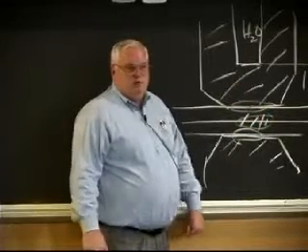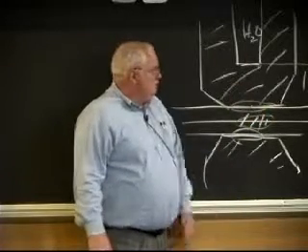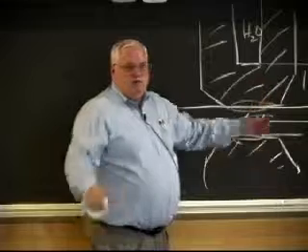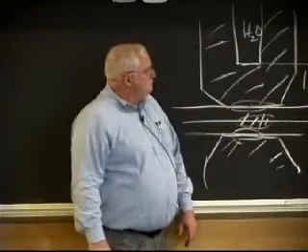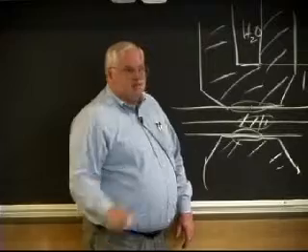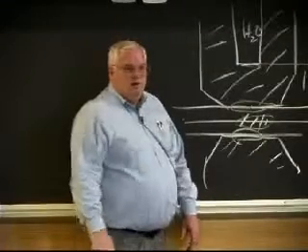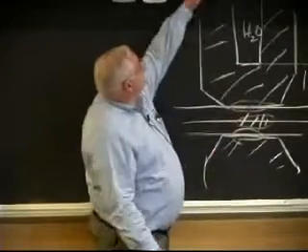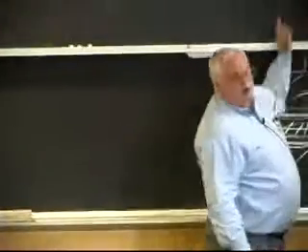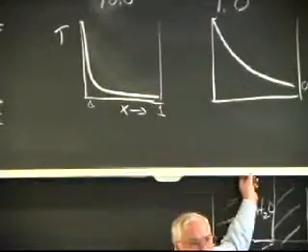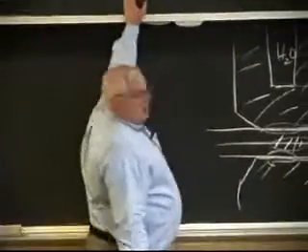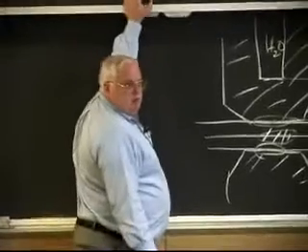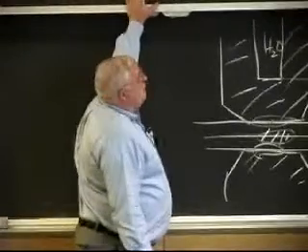You can go through it yourself. The square root of 1 times 1 is 1, the distance the heat travels in 1 second. It would take 1 second to get to this type of temperature profile, and I've only got 1/10 of a second. So this is essentially infinitely thick compared to the welding time of 1/10 of a second.